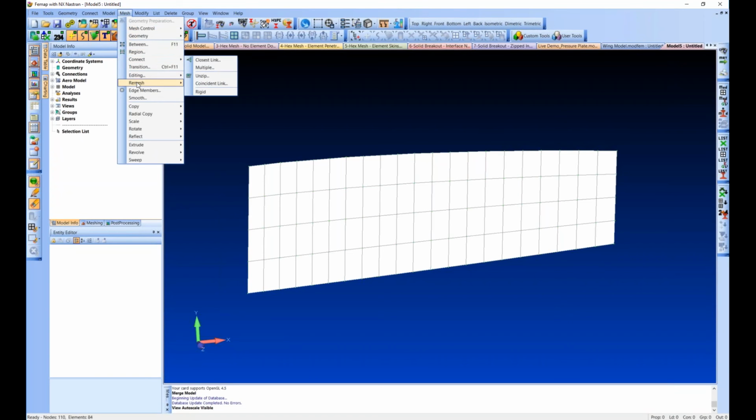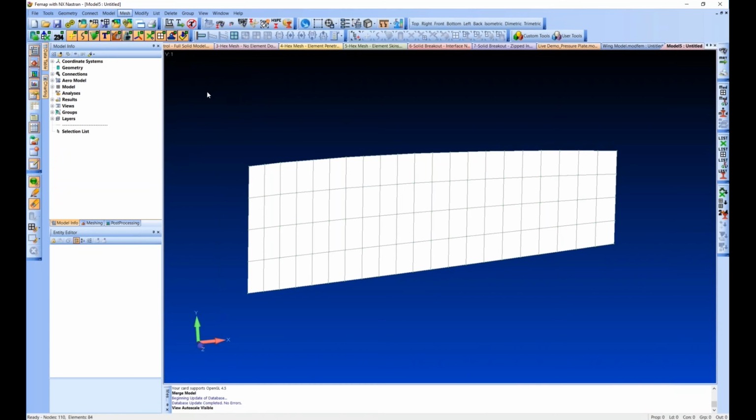It usually is better to refine the mesh instead of remeshing. The way that this maps the loads is it tries to find a node as close to the original node as possible, and if it can't find it, it has to interpolate or do some of these other methods that I'll point out later. So you're better off refining the mesh so you keep your nodes in their original location and just add more elements, more nodes.